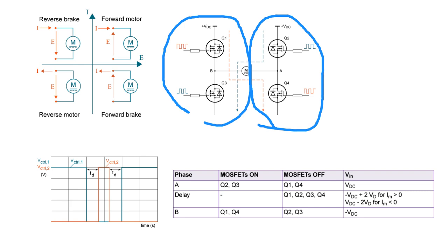The half bridge is capable of bidirectional current but not reversible voltage and thus is considered a two-quadrant one. For example, if you use only one side, yani half bridge, if you use a half bridge converter, your motor will go in only one direction. However, it works only as a motor. If you use four quadrants, two half bridge converters, you can apply forward motor application. You can use reverse brake application. Don't forget, motor operation and brake operation are different.